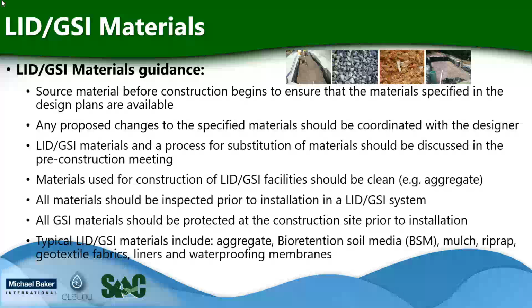Materials used for construction of LID facilities should be clean, such as aggregate should be washed. And all materials should be inspected prior to the installation of the LID and GSI system. This is critical, otherwise we'll see spiking in pollutant export from these systems.